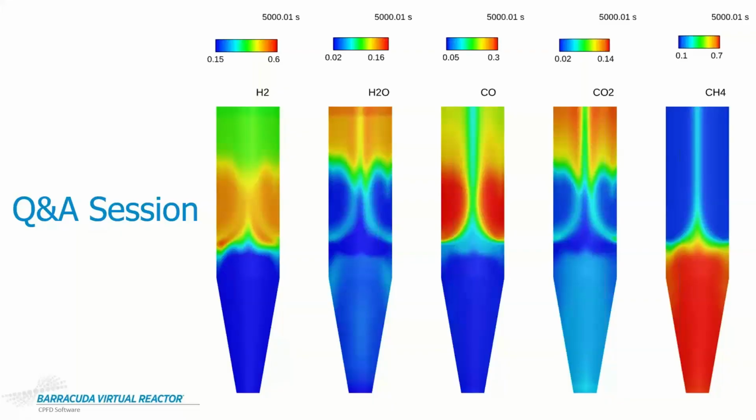So what we do is we define them in the domain. We define a pass-through probability, which will tell us how much of those particles can pass through that internal. You can imagine this can vary depending on the internal. For something like a screen that might be semi-permeable, you might have some solids that make it through. For something that's just a wall, no particles will get through. And so baffles offer the ability to model these internals without having to increase the computational complexity so much due to having to capture these really small internals.